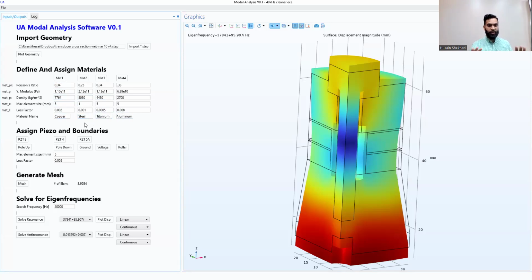What I really expect people to do at this point is to print screen when you want to document your work. You print screen, so you have all your material properties, which we change all the time. When I'm doing simulations for clients, I always notice myself changing these material properties and forgetting which graph goes with which material property. I'm always forgetting that and having to export it, and it's so much easier to just screenshot this, so you know what properties you have for copper and other things like that. So you can change these. You can change the Poisson's ratio, like here.